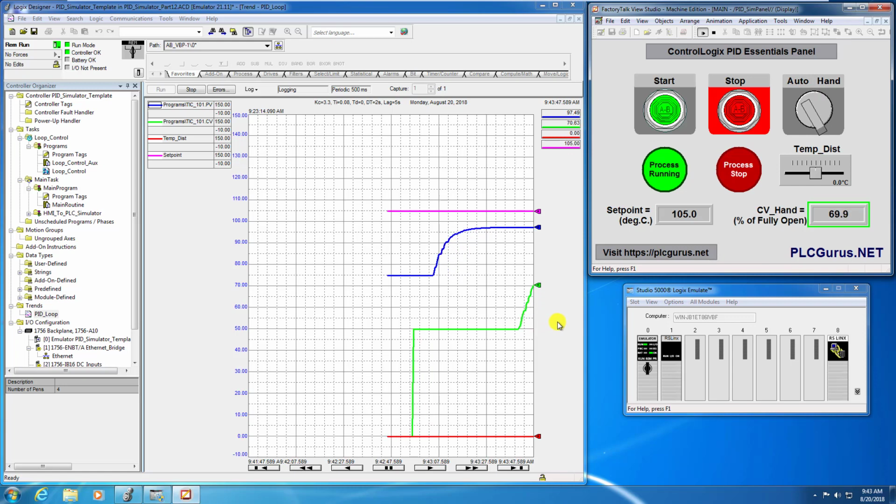So remember now, the negative effects of dead time are that we are making changes, but we're not seeing what the impact of that change is until some period later, 8 seconds later, which could cause issues, right? We're making a change in our output, our steam, but we're not seeing what the impacts of that change are straight away. We're seeing it some period later.